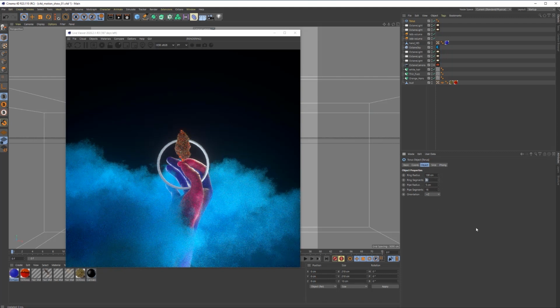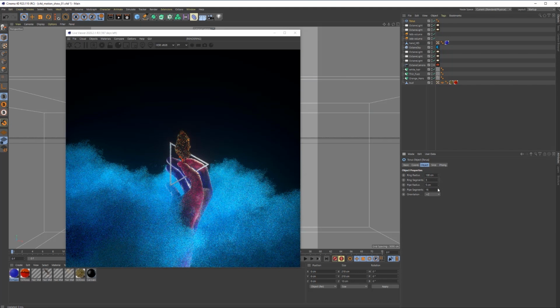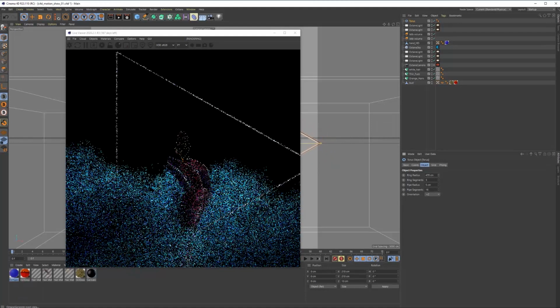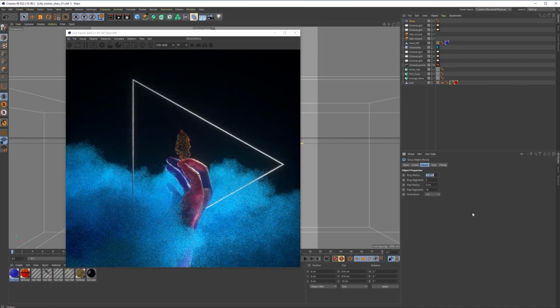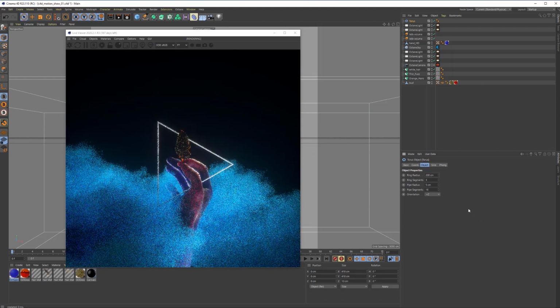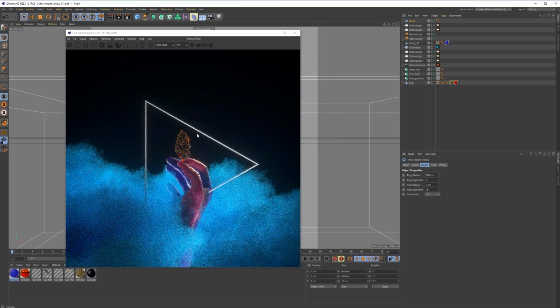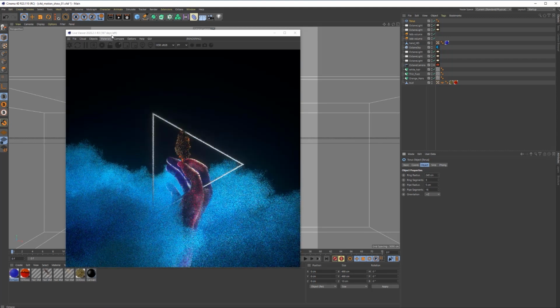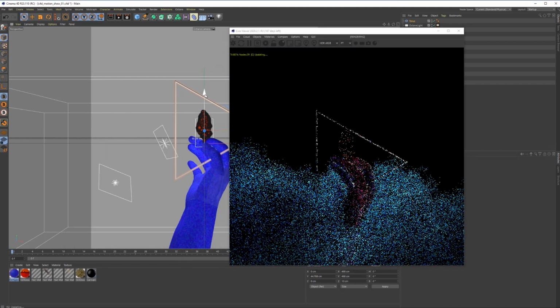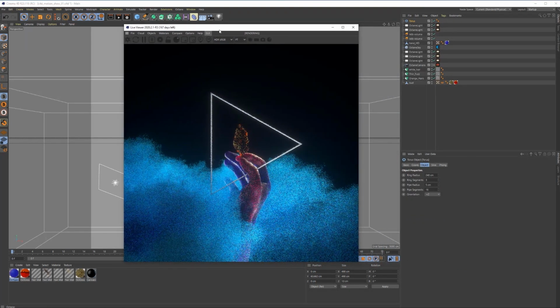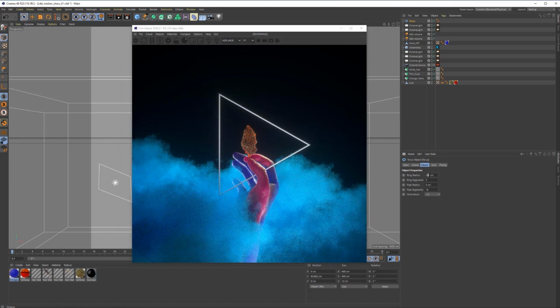Let's do the, what is it? Is it the ring segments? Let's bring this to 3. Yeah, there we go. And let's scale the radius of this. Well, not that much. Let's say what 200 looks like. Let's go with 300. 240. All right, let's stick with 240 for a minute and let's push this up. All right, so this is going to create some sort of framing. Maybe 250.